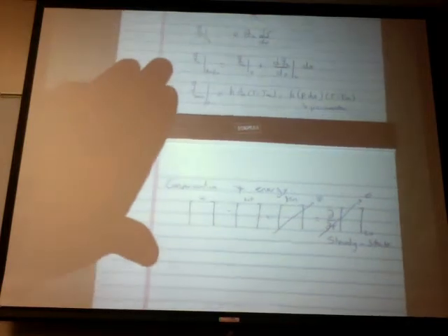And generation meaning that whatever material this fin is made of, there might be some kind of chemical reaction inside that has internal heat generation. We're assuming that that's zero. It's just a passive metal that we're using, as it is used in all cases of fins.